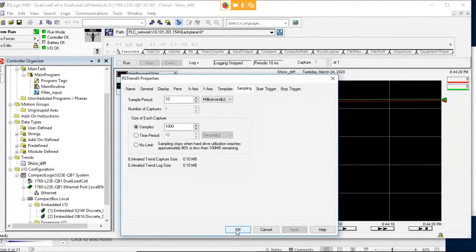And then as we know from doing our little timer exercises in class, even a 5-second timer when you're sitting there waiting seems to be forever. So sampling is how often it's going to plot a point on here. So I was doing it every 10 seconds, right? So that was all 1001, 1002, 1003, 1004, 1005, right? All the way up to 10 before it actually created anything. So that's why I wasn't waiting long enough. So your sampling, you want to be fairly quick. Now, the catch is if you make sampling too quick, you overload your computer. So that's why they give you these different choices.